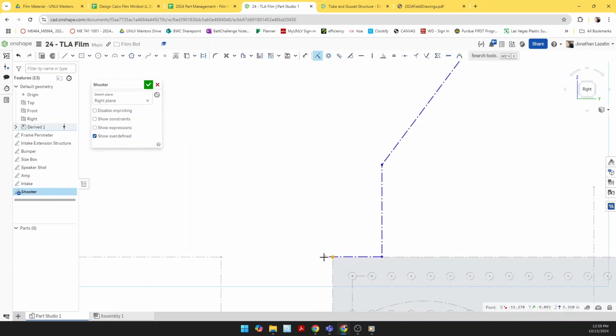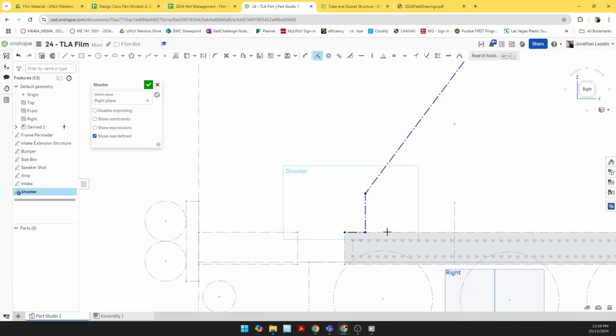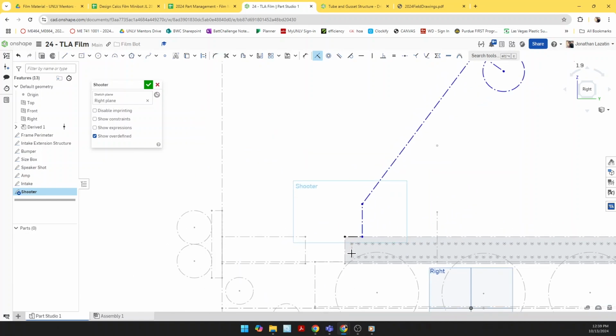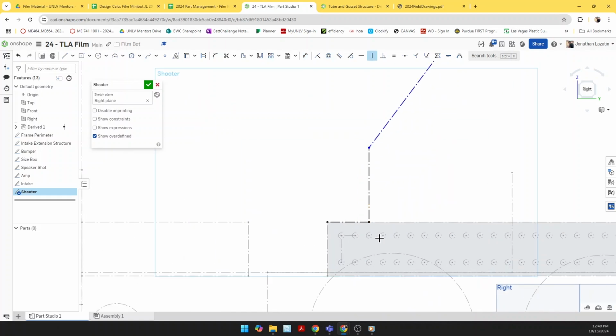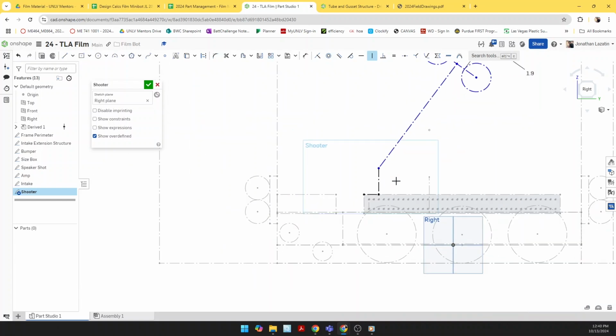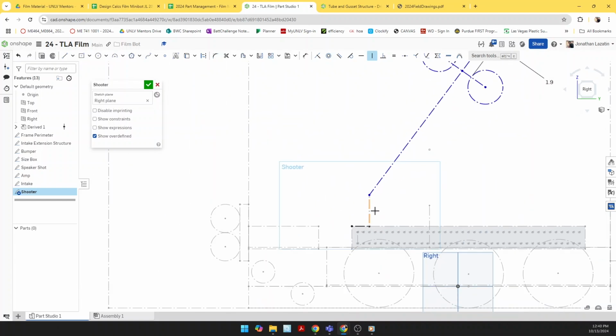Whatever plate I design to hold that axle, I'm going to reference this back edge here. I want that to be vertical. So I'm going to use probably about 5 holes here to get this location. I know there's some electronics back here, so I want this arm pivot to be a bit higher.